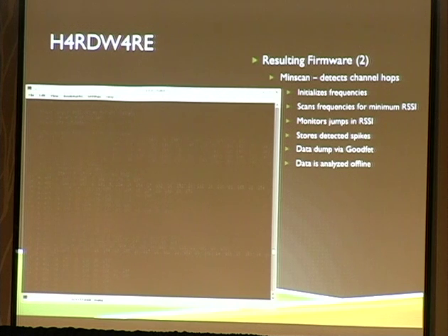What this culminated in is what we're calling MinScan. This is taking the idea that when you're monitoring a device that is doing frequency hopping, there's always going to be a minimum level of noise. So we take that information, reverse from the max scan and start looking at the minimum that we're seeing within the environment. Pull that in, store that, and then add a minimum value of RSSI. We're monitoring the RSSI value and seeing when a frequency jumps above that range.